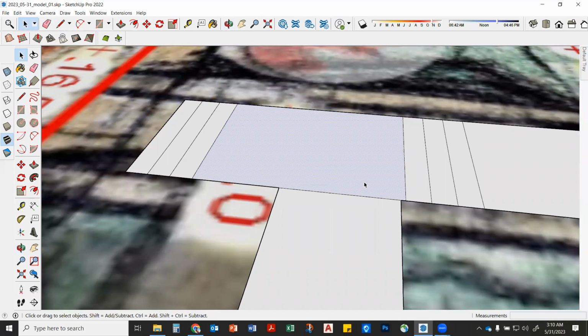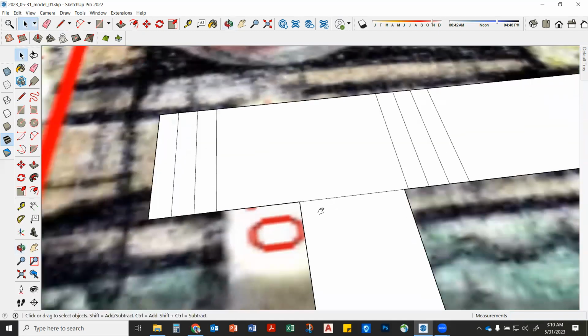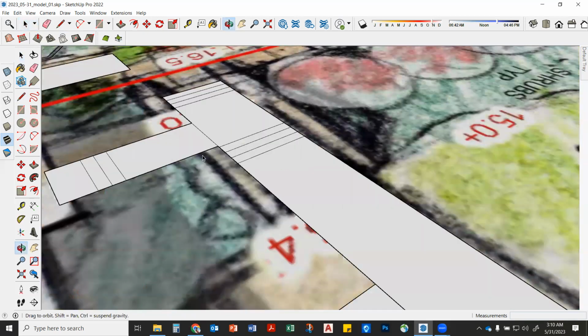So some of you guys, when I was helping you earlier, if you're making a face and it looks like it's kind of flashing, like purple and white, that means you have two faces. So you can generally just select one of them and delete it. I only have one, so. But if you're coming into that issue, ask and we can fix it.